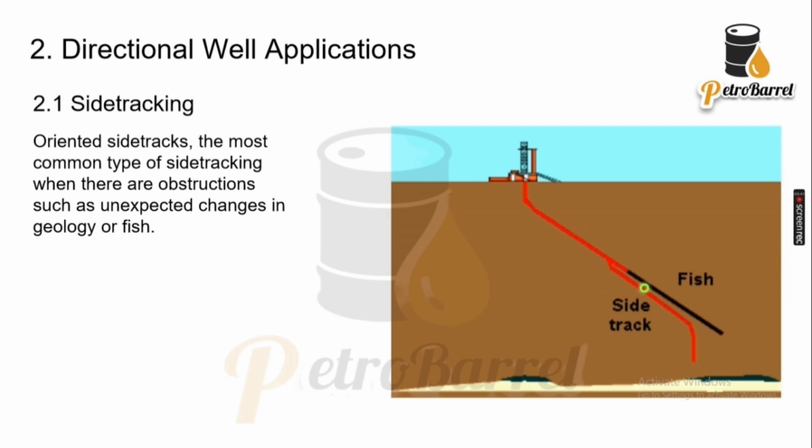So the question now, what should you do if the pipe is stuck? Simply we will use a jet cutter to cut the drill string through this part, for example, then pull out of hole, then connect a new drilling bit, then run in hole and make a side track to reach our reservoir. So this jet cutter video describes the equipment of the jet cutter and how we use it.